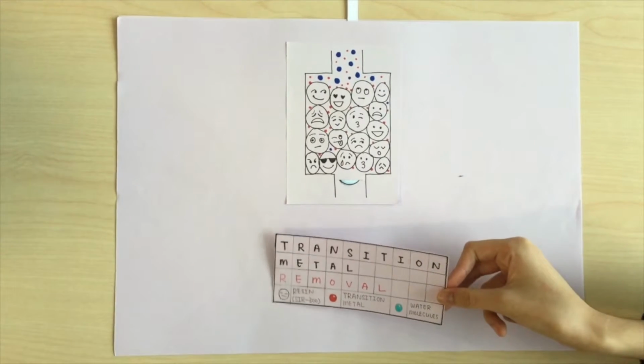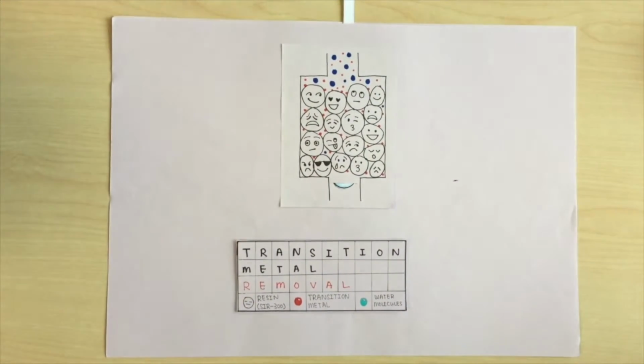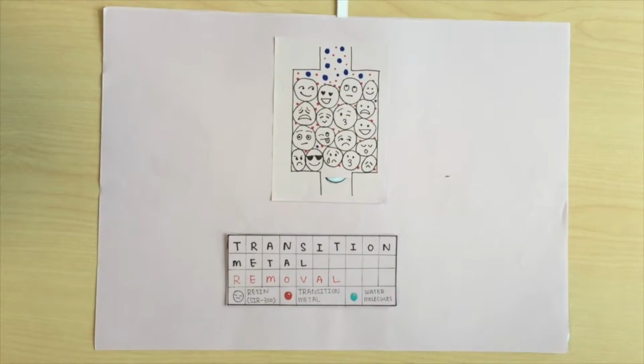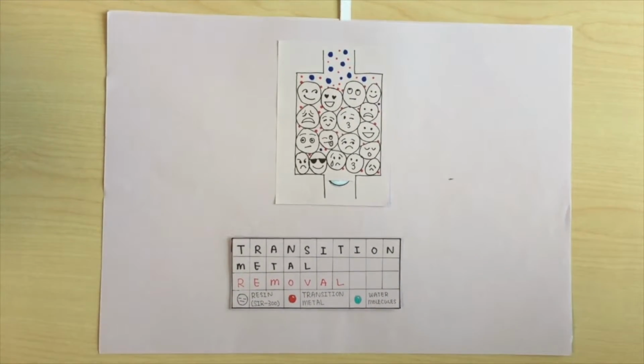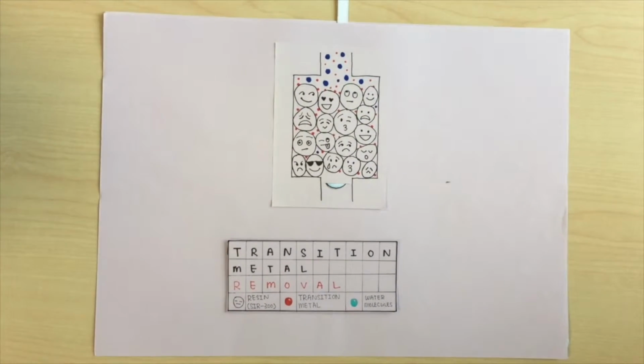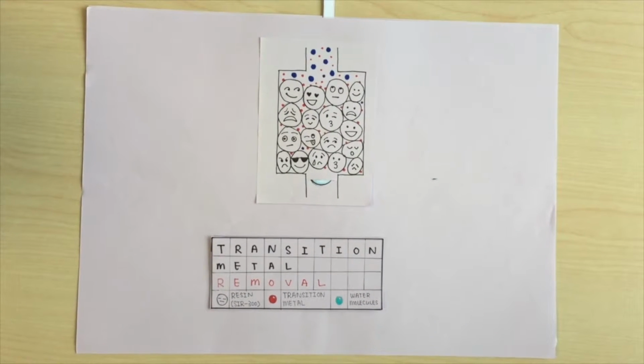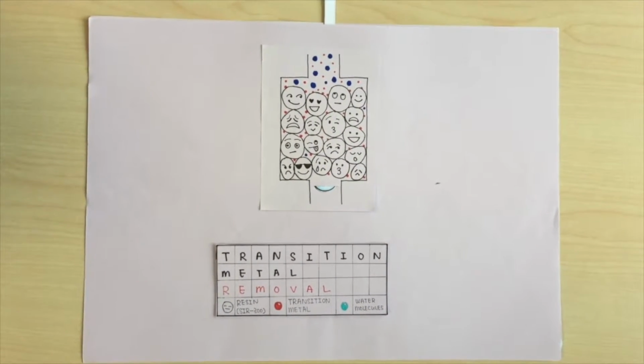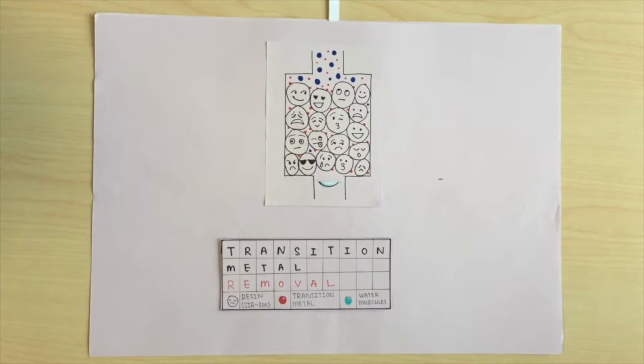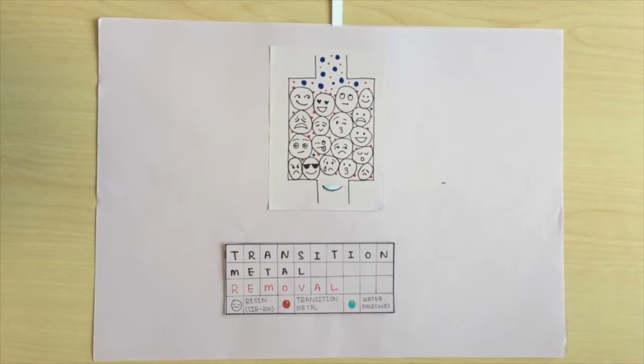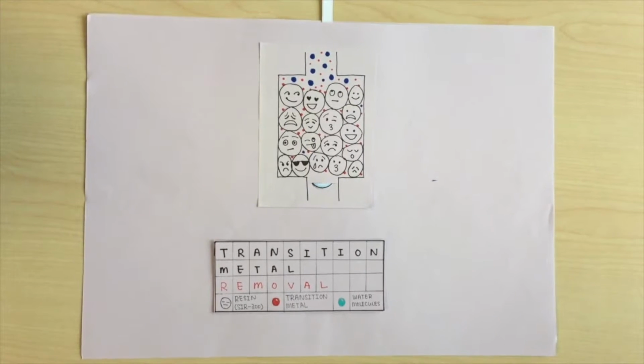We are going to remove transition metals after arsenic removal. As the concentration of transition metals in groundwater is definitely higher than surface water, we need to remove transition metals carefully. Chelated ion exchange resin usually has a higher preference for transition metals, so transition metals can be removed clearly